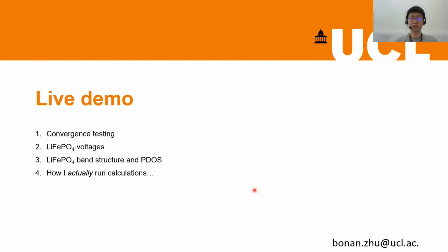Each MPI process will still take 8 gigabytes of memory. But if you use NCORE equals 2, each will take 4, and the same for NPAR. However, the k-point distribution is the most efficient. You'll find that the KPAR equals 2 calculation is faster than NCORE equals 2 or NPAR equals 2 in this simple example.